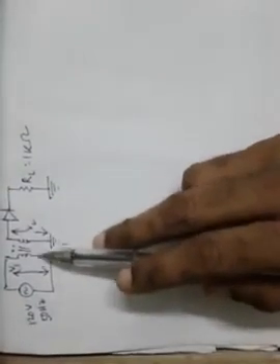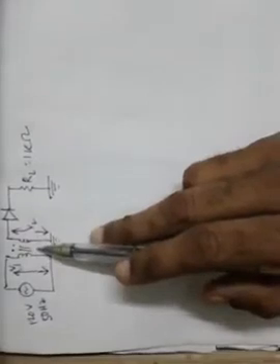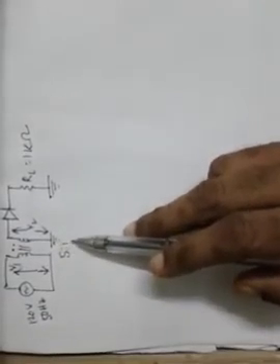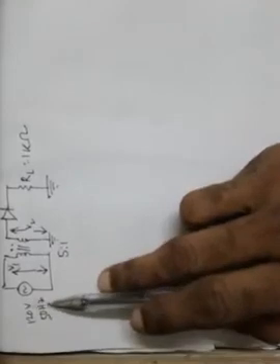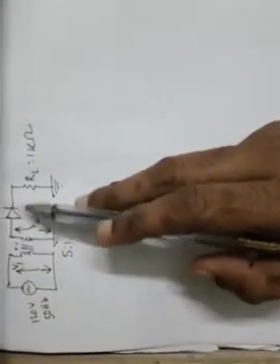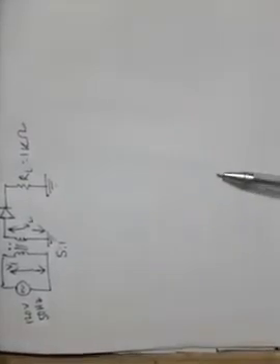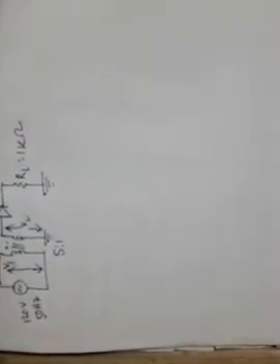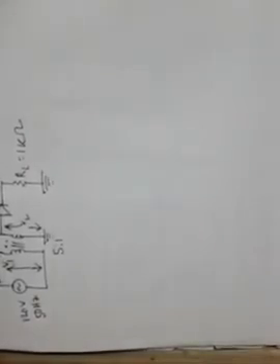It is a step down transformer with 5:1 ratio. At the primary side, a 120 volt 50 hertz AC signal is being applied. A diode is connected. Since it is a single diode, this is nothing but a transformer connected half wave rectifier, and RL is the load of value 1 kilo ohm. So given this circuit, you need to calculate the peak load voltage and DC load voltage.